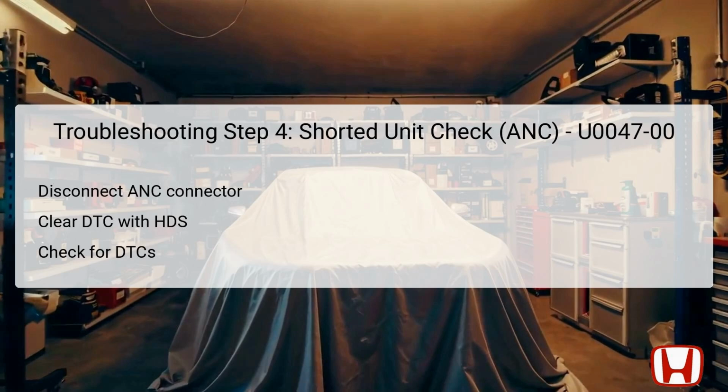The fourth troubleshooting step involves assessing the ANC, active noise control unit, for any signs of a short circuit. Just like previous steps, ensure the vehicle's ignition is turned to the off position prior to starting this check. Begin by disconnecting the ANC unit, which typically uses a 20P connector. This component is crucial for noise cancellation during vehicle operation.